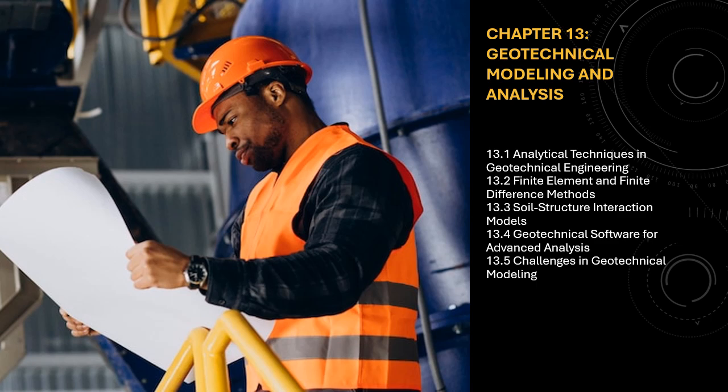13.2.1.2 Applications of FEM in Geotechnical Engineering. Soil-structure interaction, SSI. FEM is particularly effective for modeling soil-structure interaction problems, where the interaction between a foundation and the underlying soil needs to be analyzed. It is used to simulate the response of foundations under static and dynamic loads, such as in the analysis of buildings, bridges, and retaining walls.